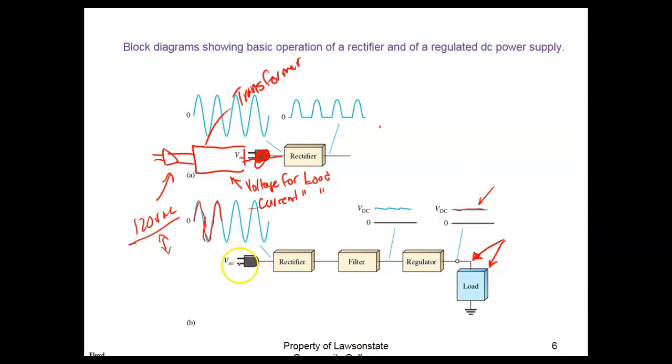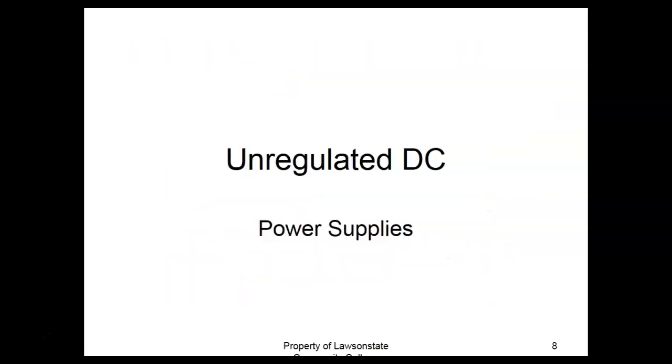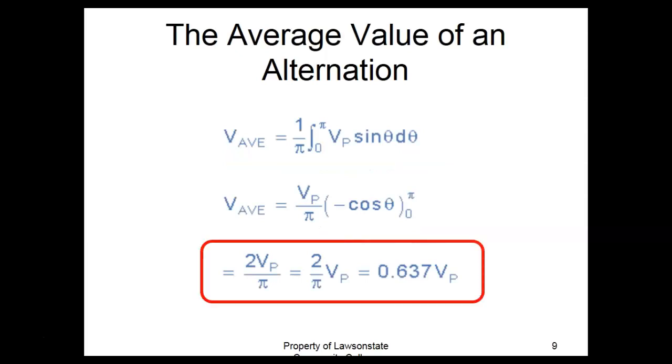But the one thing to note, on 90% of the linear power supplies, the first thing we're going to have is a transformer. And most of the time it's a step-down transformer. Of course, we know the advantage of a lower voltage is that we can deliver the power more safely. But the current has to go up to deliver that power, right?